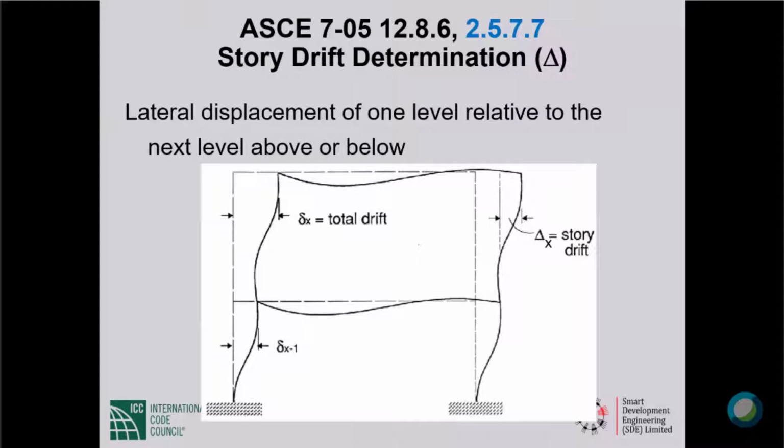Most of the seismic design provisions of the code are life safety provisions or collapse prevention these days. Remember, we design to prevent collapse in the maximum considered earthquake. Most of the provisions are directed towards ensuring that. But in two places in the code, we go beyond strict life safety. Once when we introduce an importance factor larger than 1 in the design of higher occupancy category structures, and second, when we do a drift check, the purpose of which is to make sure that non-structural components are not damaged because of too much interstory drift.